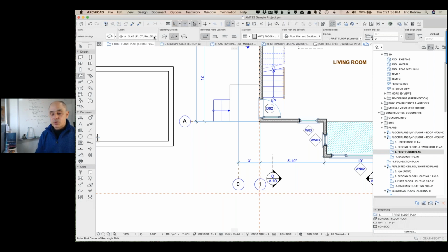But of course, some tools are used on multiple layers. In fact, in general, that's a common thing. Slabs can be used for floors or ceilings and tabletops sometimes. Objects, of course, are used on all different types of layers, furniture and landscape and equipment, etc. So while you can't just switch a tool, if you want to make sure you're on the right layer, then eyedropping an element that already exists on that layer is the ideal, or using favorites.